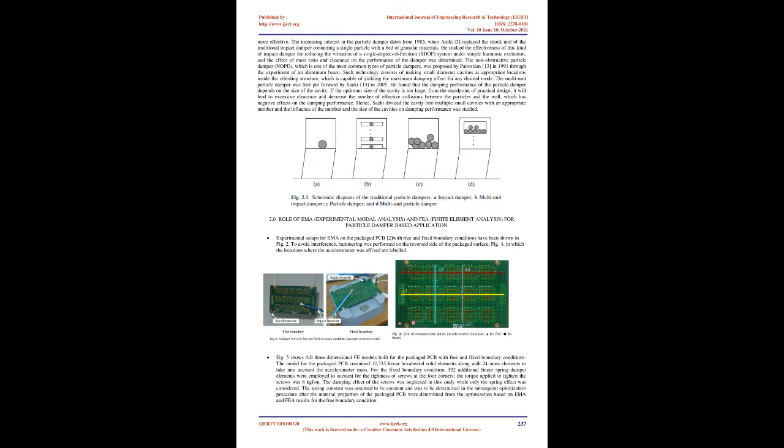The non-obstructive particle damper, NOPD, which is one of the most common types of particle dampers, was proposed by Panossian [13] in 1991 through the experiment of an aluminum beam. Such technology consists of making small diameter cavities at appropriate locations inside the vibrating structure, which is capable of yielding the maximum damping effect for any desired mode.